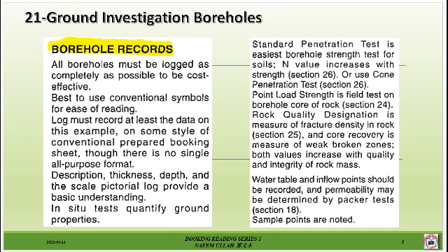Borehole records. All boreholes must be logged as completely as possible to be cost effective. Best to use conventional samples for ease of reading. The log must record at least the data in this example, on some style of conventional prepared logging sheet, though there is no single all-purpose format. Description, thickness, depth, and the scale pictorial log provide a basic understanding.